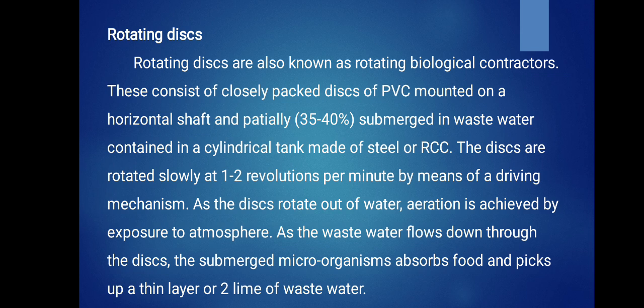This rotating disc is also known as rotating biological contactors, RBC. These consist of closely packed disc of PVC mounted on a horizontal shaft and partially submerged in wastewater contained in a cylindrical tank made of steel or RCC.